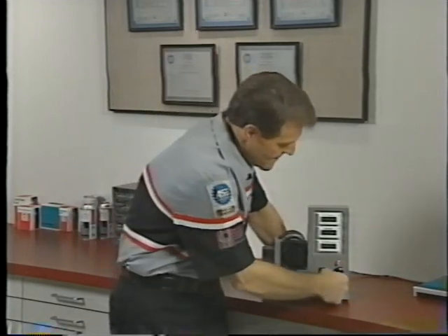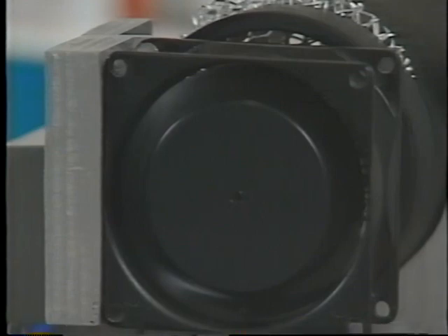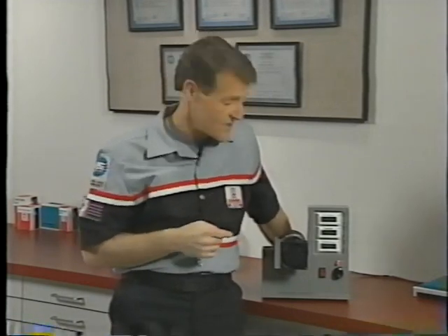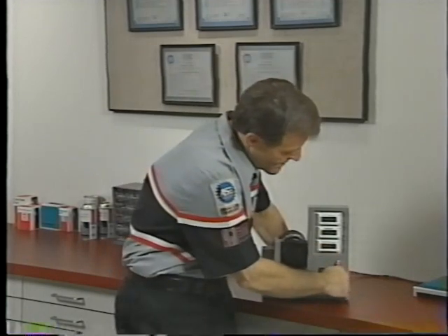Let's turn the fan up to medium speed to simulate increased airflow into the engine. This causes a greater cooling effect, and again, wire temperature decreases. Again, I increase the heating current until I see the wire is at 95 degrees Celsius. You see the pattern? Each time the cooling effect increases, I increase the current to compensate. The same happens in reverse. If airflow decreases, there is less cooling effect and I can use less current.